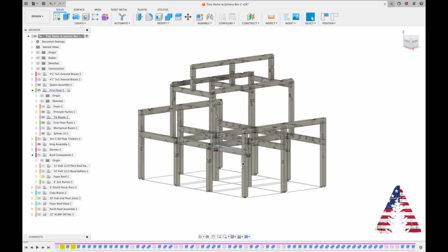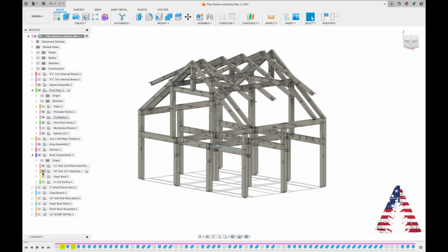Very large structures in medieval Europe were timber framed, and they were tall, large structures. But the principal purlin design is all integrated together, and the strength of the frame is entirely in this assembly that you're seeing here. And the rafters, when I put those on top, really just become beams at an angle. So if I put the roof components back on,